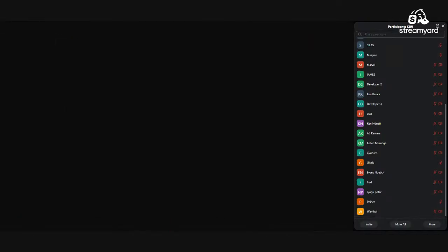And if I go to add an annotation table, I'm going to see that this pipe, for example, is 200 millimeter, the flow is 1.1 liter per second, and that is my slope. So I get all the information of the manhole and all the information of the pipe, and I can also go to my profile here and see it as an engineering profile like that. I can also export it to AutoCAD.